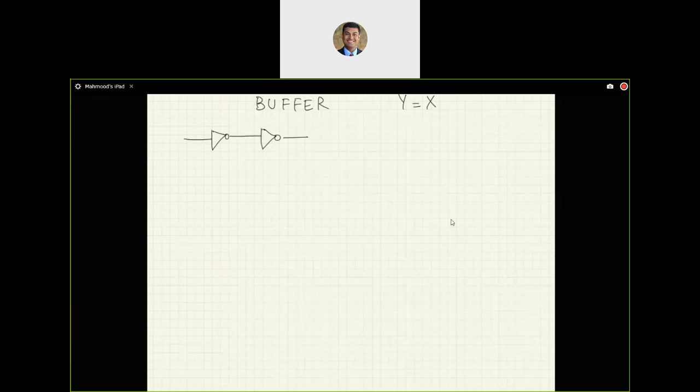So what I'm going to do is I'm going to take one transistor and I still have the pull-up resistor to say 5 volts, and this is my Vx. This is the base, this is the collector, this is the emitter. So far I have one NOT gate. I need two of them.